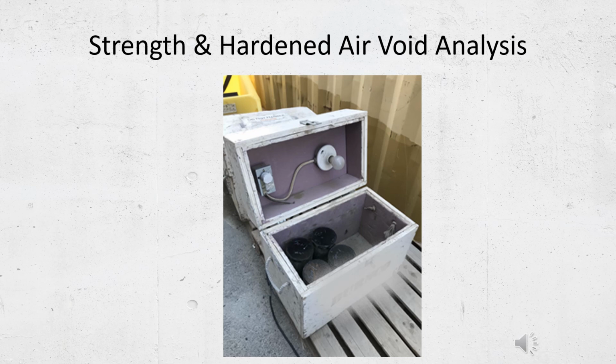All field tests shall be conducted and concrete test cylinders shall be cast by a certified testing technician in the presence of the auditor at the time of the audit and collected by the auditor's lab the day following the audit.